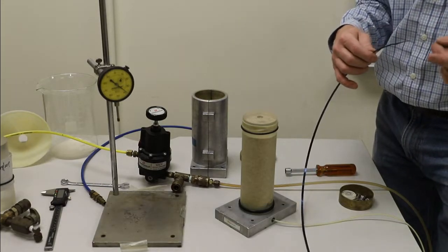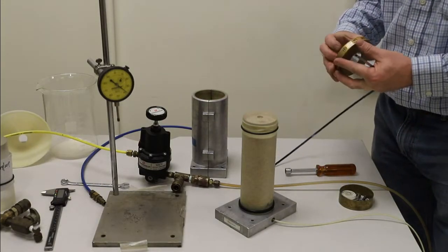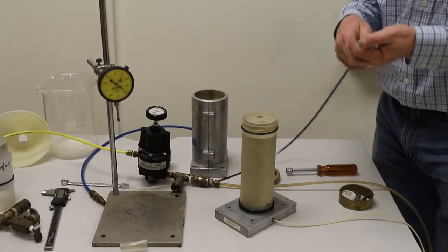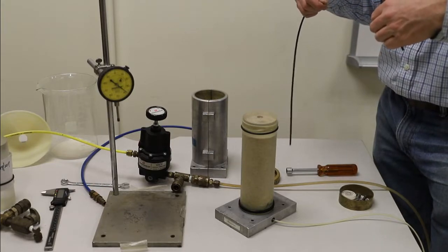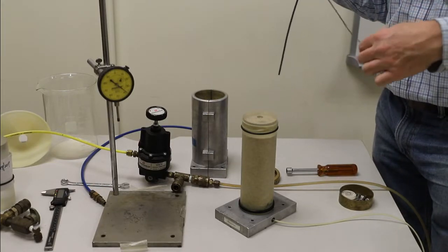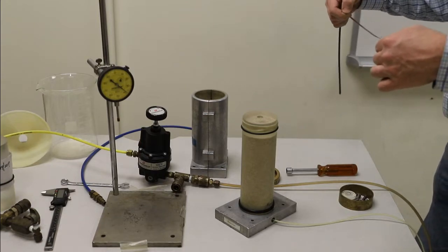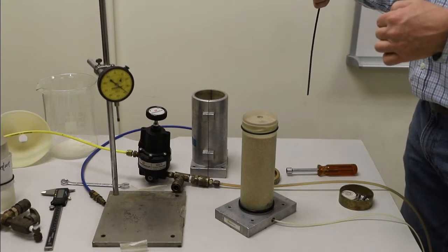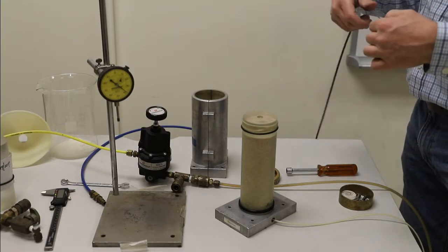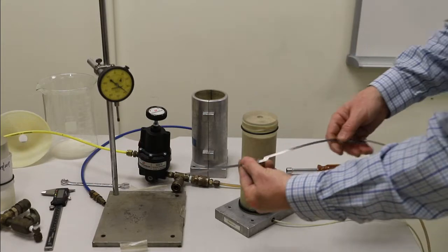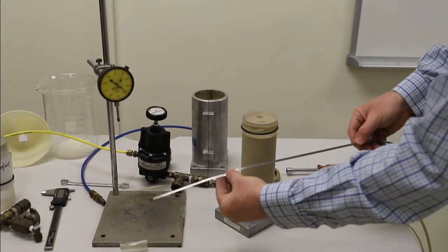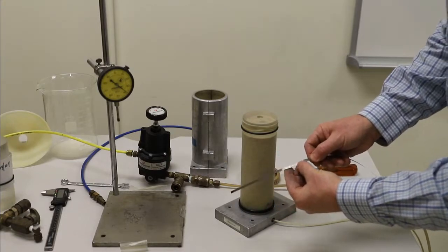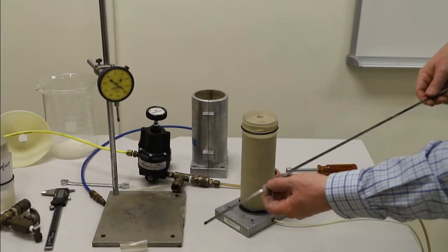Another alternative is to use this ingenious little thing, which has been around for a while. It's called a pi tape, P-I. This one say that? Yes, it does. So pi tapes are clever in that they are flexible rulers, essentially. They have divisions. This one is in inches, but it measures to the thousandth of an inch. And the way that it can do that is it has a main scale. There's a main scale on this top major part of the system. And then it has a vernier caliper scale on this little dog leg here.